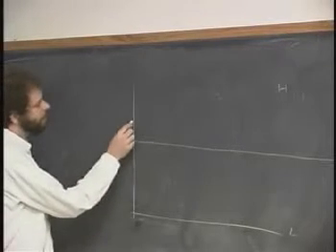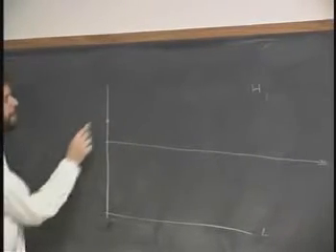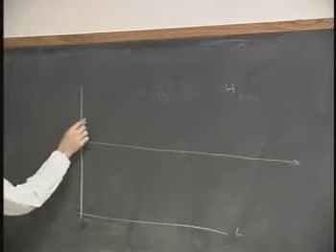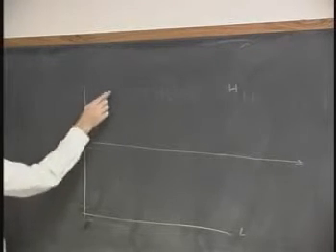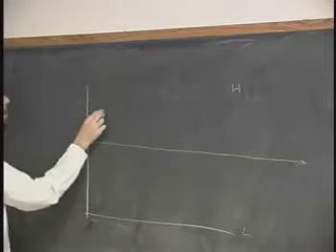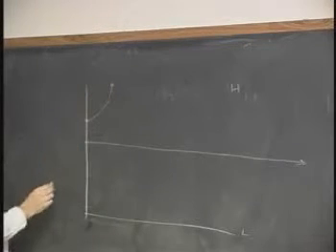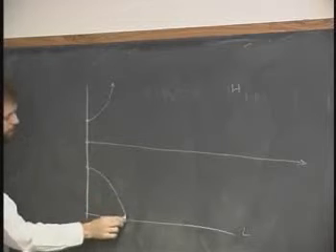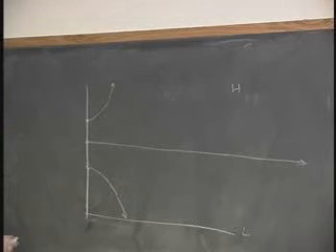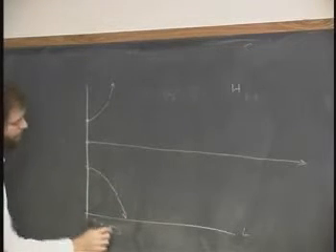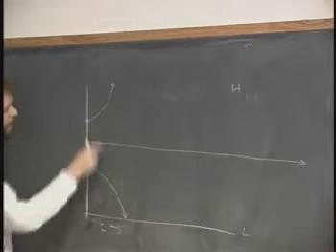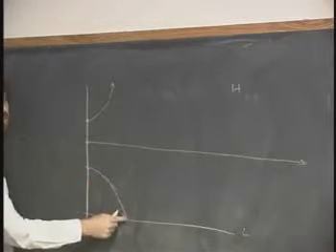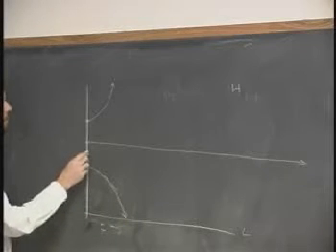But if I started them out, let's say over here, then chances are it'll become a high, but it will start out sort of at this speed, and then the closer it gets to going high, the faster it goes like that. And if I started out over there in exactly this symmetric case, it'll go towards low like that. In other words, as time goes by, the closer we get to being either low or high, the higher the slope is, the faster the slope is towards getting there.